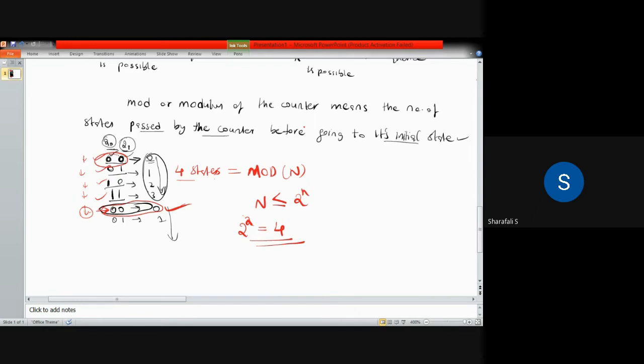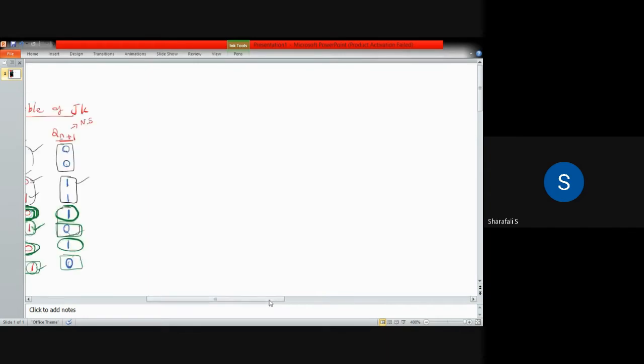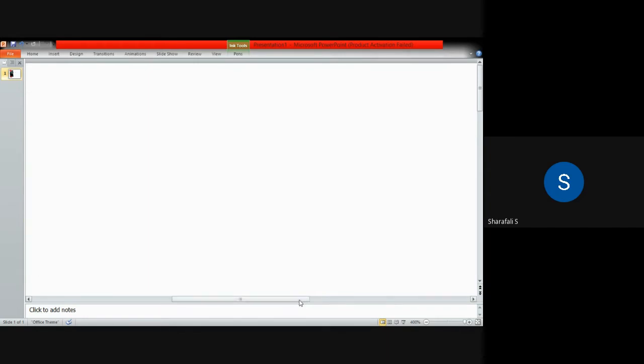Now we will go to the synchronous counter. We will discuss the different steps you need to follow to make a synchronous counter. First, we have to consider how many flip-flops you require, and also the type of flip-flops.